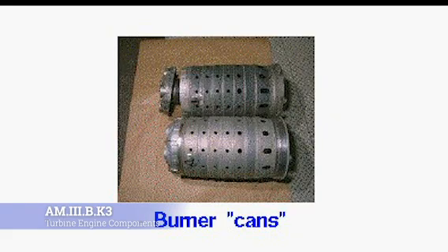Okay, so every combustion section is going to have five things in common. They're going to have a casing, an inner liner that is perforated, some sort of fuel injection system, some means for initial ignition, and then a fuel drainage system. All of those can be rearranged into four basic types of combustion chambers: the can type, like you're looking at here, the can annular, the annular type, and the reverse flow type. Let's talk about the burner can first, because once you understand the can, the rest of them kind of fall into place.